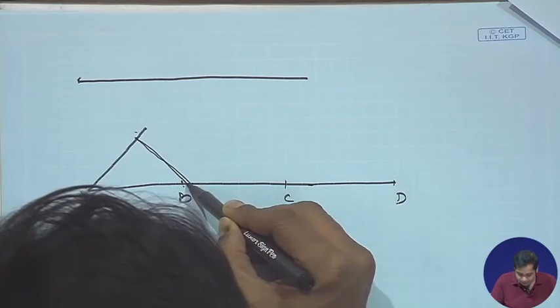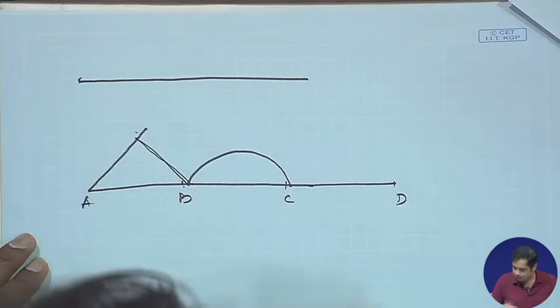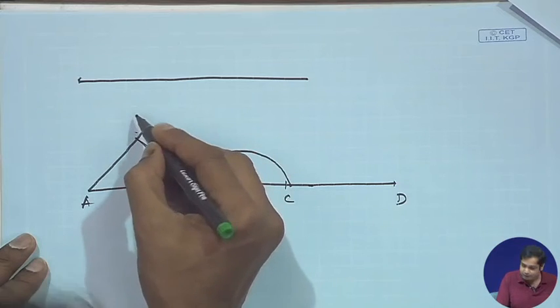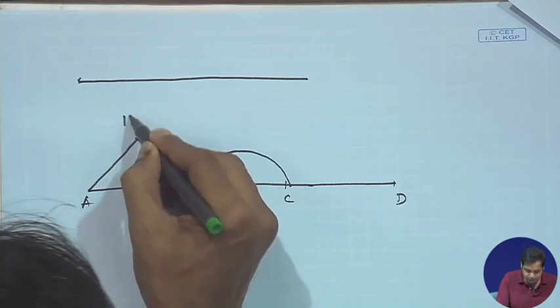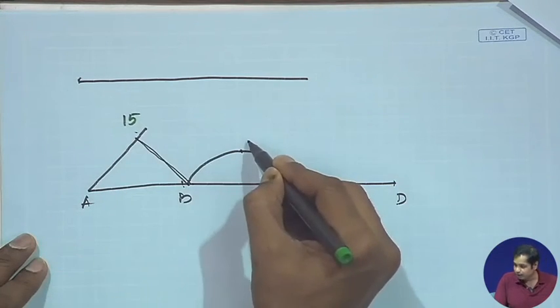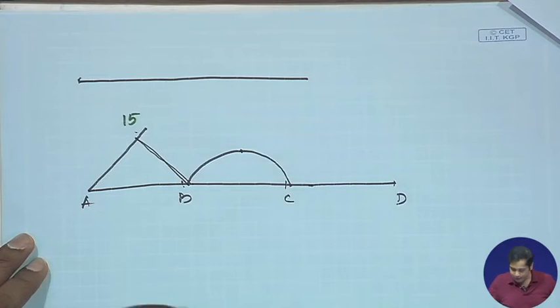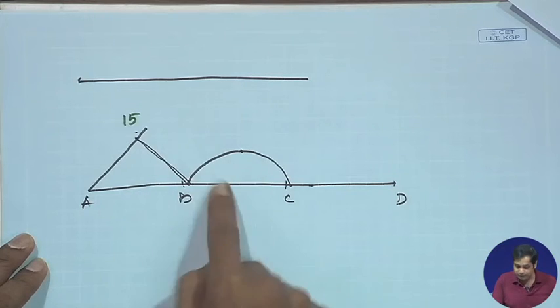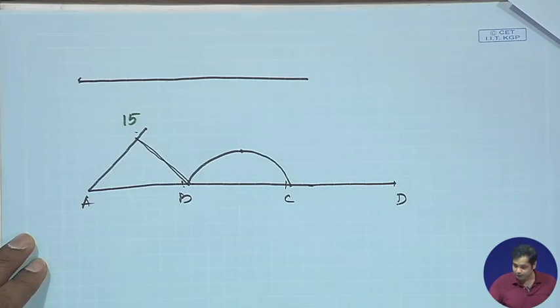And then, okay. So, this value is 15 and this value is, we know that, 8.4. Okay, and there is no bending moment at C. These are all positive bending moments, right? Because according to the sign convention we take, these bending moments are positive.